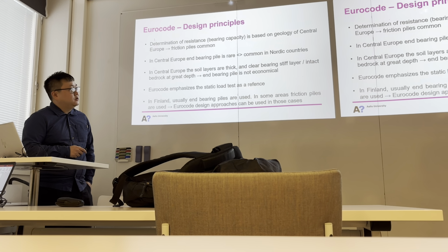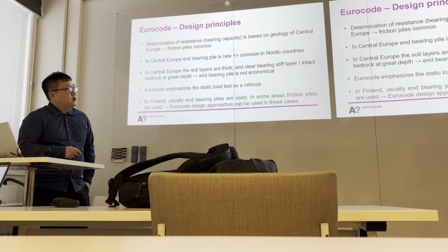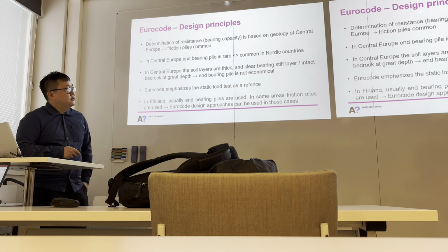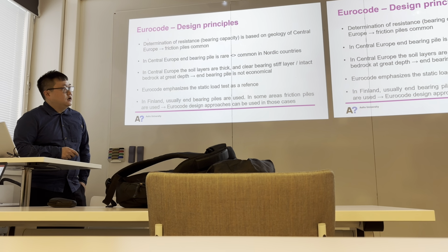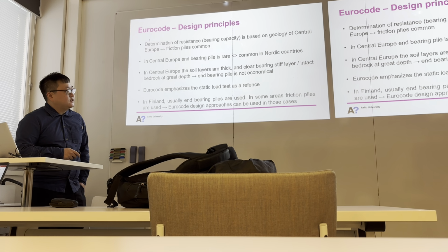And in Central Europe, the end-bearing pile is not often used, but in Finland and Sweden, it's very common. In Central Europe, the soil layers are thick, and the clear bearing stiff layer or the bedrock is at great depths. So the end bearing pile is more expensive. Based on this, Eurocode emphasized the static load test as a reference. But in Finland, because we often use the end bearing pile, we prefer the dynamic load test as a reference for the design.